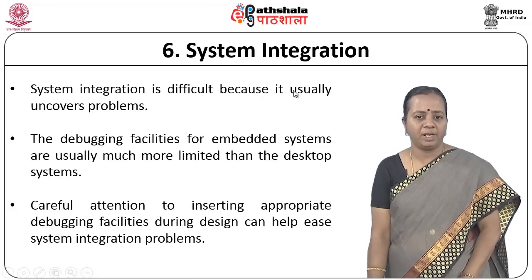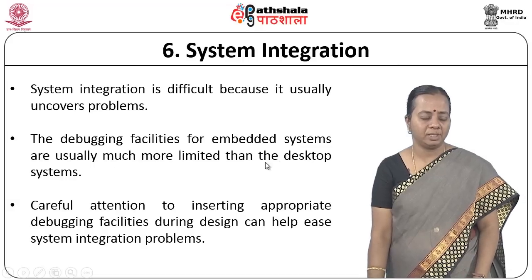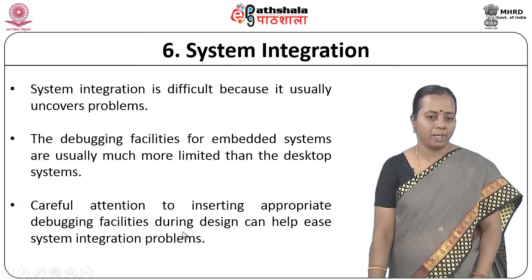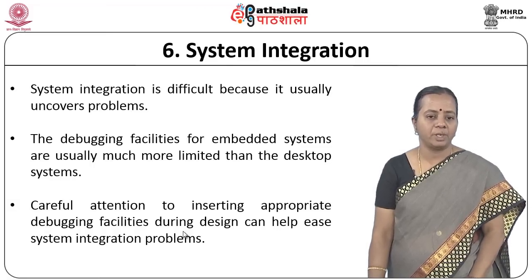Integration is very difficult because it usually uncovers problems. The debugging facilities for embedded systems are usually much more limited than on desktop systems. So careful attention to inserting appropriate debugging facilities during the design can help easy access to system integration problems.